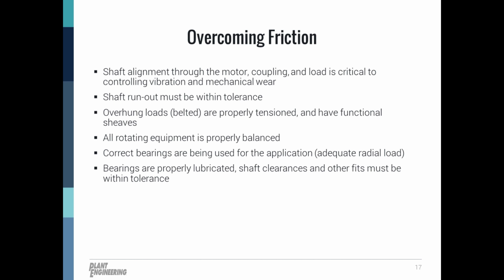And remember that bearings should be maintained based on run hours. So there's product literature out there from the bearing manufacturers that can give you specifics, details on lubrication types, intervals, and the amount of grease to add.